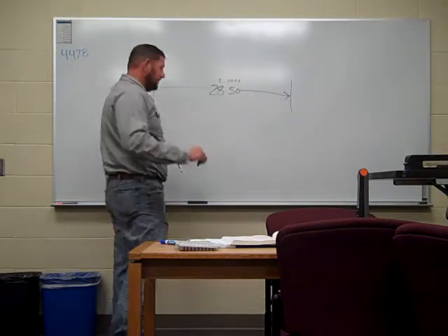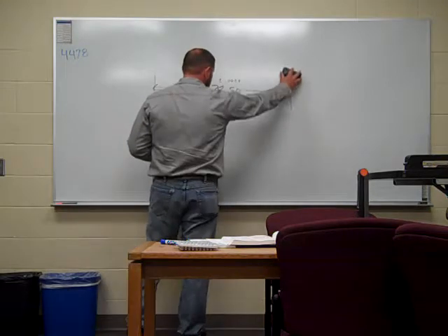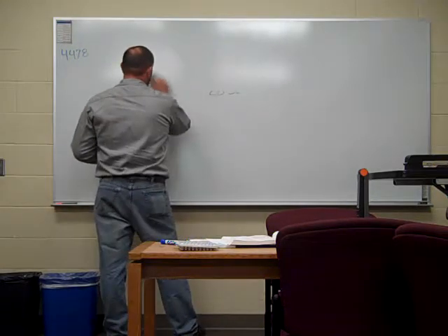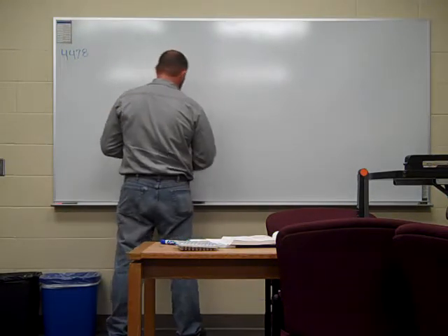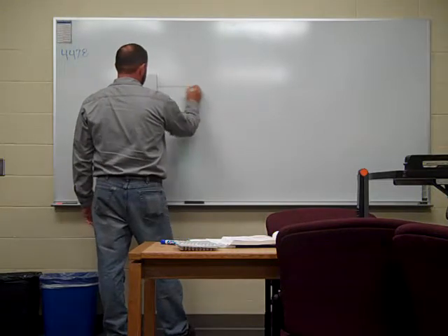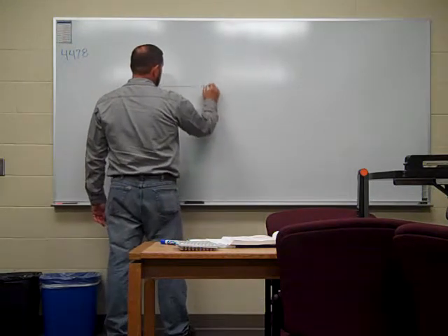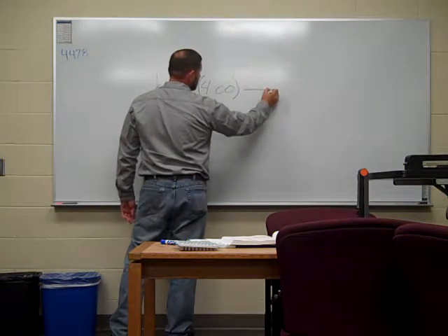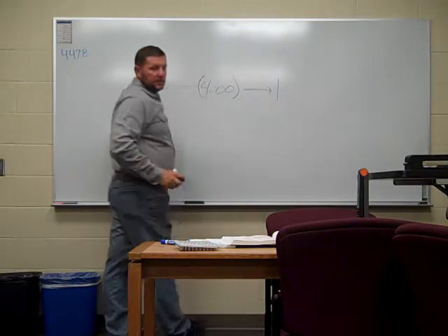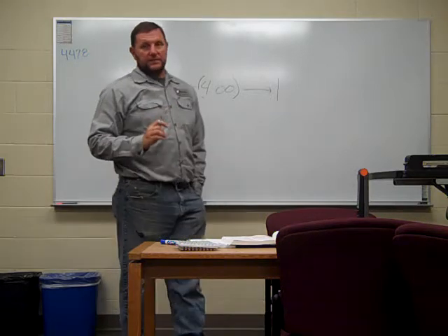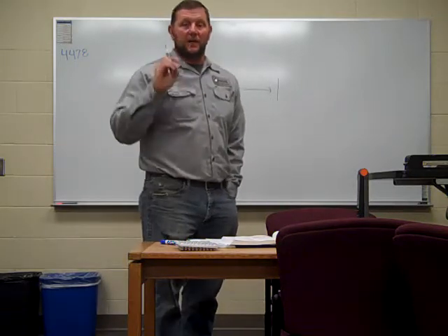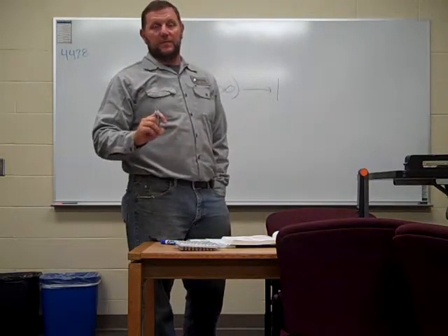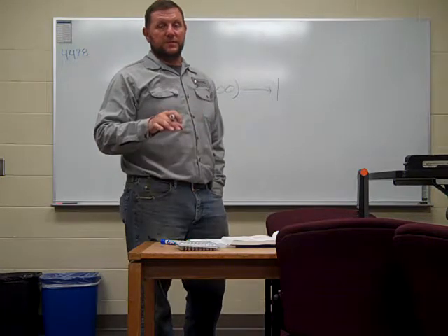And as you get to the right, there's something they call a reference dimension. What is a reference dimension? They use the example 4.00. It's in parentheses. When you see that in parentheses, tolerances don't apply to that reference dimension. It's just a reference.